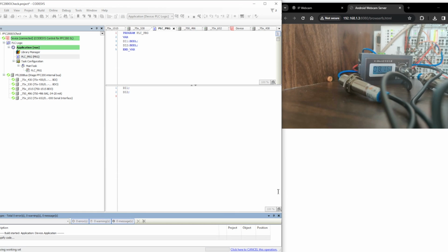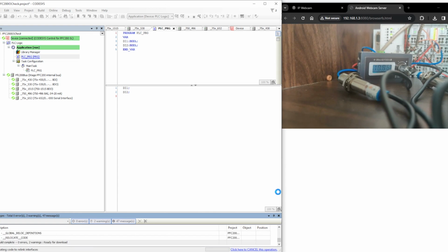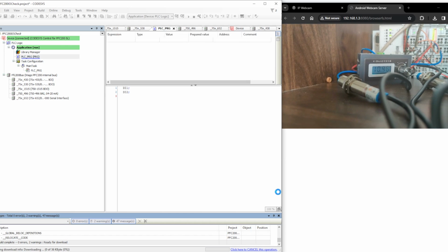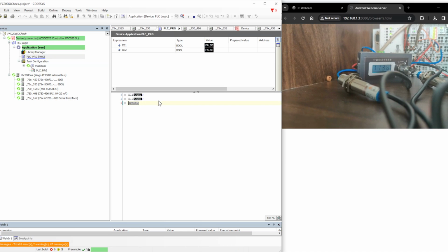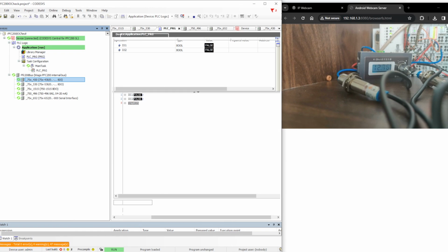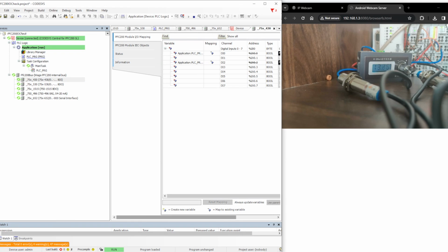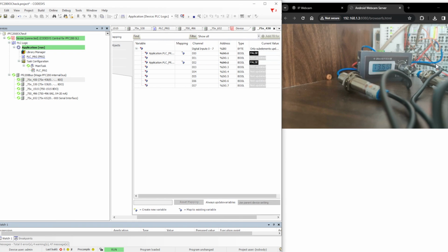It will not be grayed out, and it will be showing a value either true or false based on the condition of that particular IO or that particular channel. Okay, so now we have utilized this in the program, and now if I go back to the DI card and double click, yeah, here we see that these two channels are in the false state, because the status coming on those channels is false.